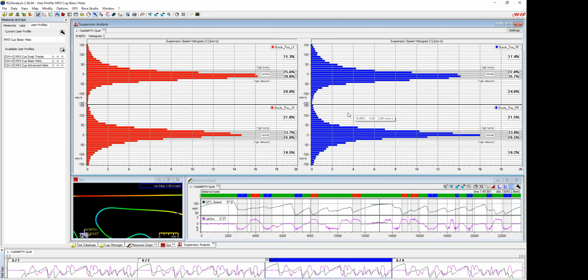Okay. The one set for the weekend, do shock settings tend to hold for the next track next week? Certainly the settings tend to hold. The shocks are pretty robust. Obviously they're being beat up and down the track, but you're not going to change that shock a ton by having it bolted into, strapped into the trailer and the trip back to the shop and then back to the next track. But the track will change. If you go to Lime Rock one day and you're at Daytona the next, or Pocono, something that's got some roughness to it, you may need to adjust your shocks to get these numbers in there. So it's more track specific than week specific.